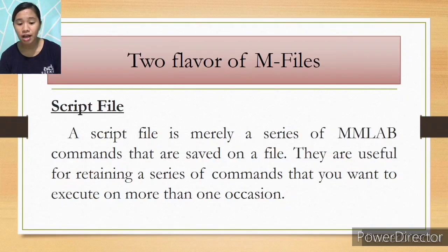A script file is merely a series of MATLAB commands that are saved on file. They are used for retaining a series of commands that you want to execute on more than one occasion. The script can be executed by typing the file name in the command window or by invoking the menu selection in the edit window. Try to find the debug and run.